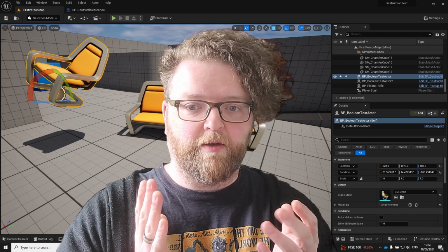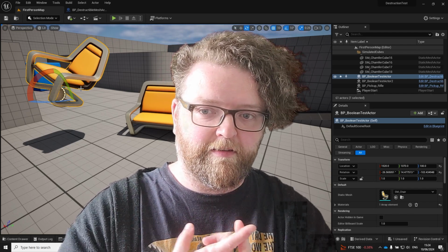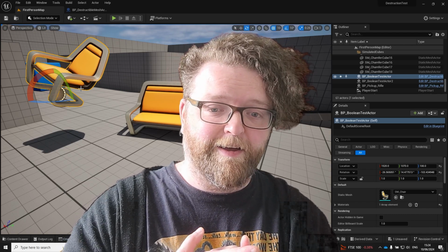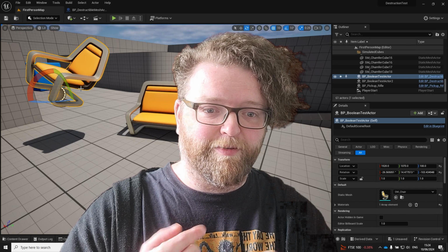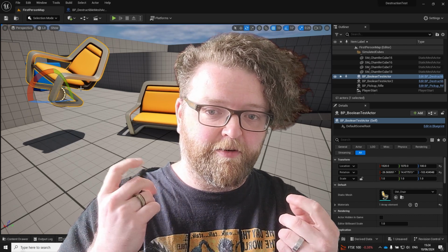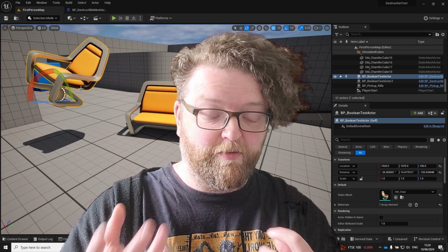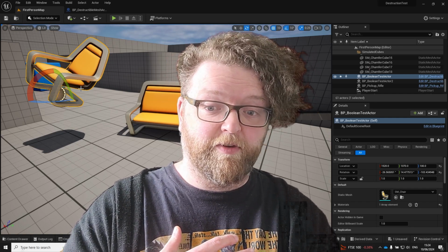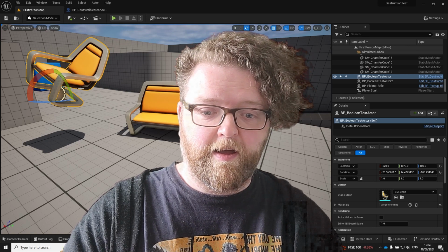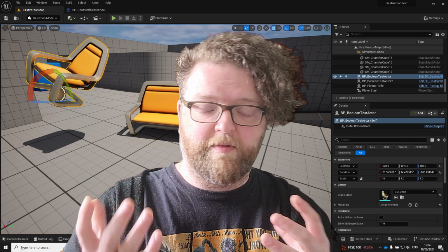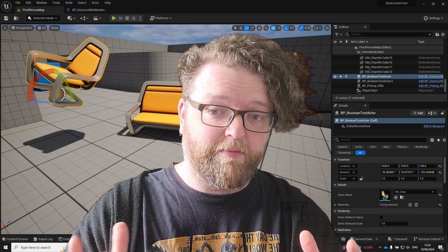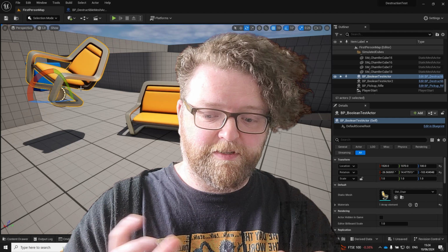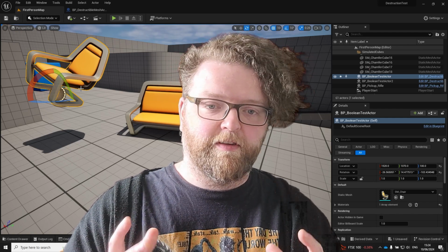There's loads of stuff I would do. Things I skipped in this video. I didn't play with the collision channels. The debris is really annoying. If you set up collision channels, you can make sure that the debris collides with other static objects and collides with itself, but doesn't collide with the player, and that makes moving around a lot nicer. I didn't have the debris disappear after a little while. Other than that, I didn't add Niagara particle effects, which would be the next thing to sort of mask a little bit of the awkwardness of the explosion. But there's loads you can do with this.